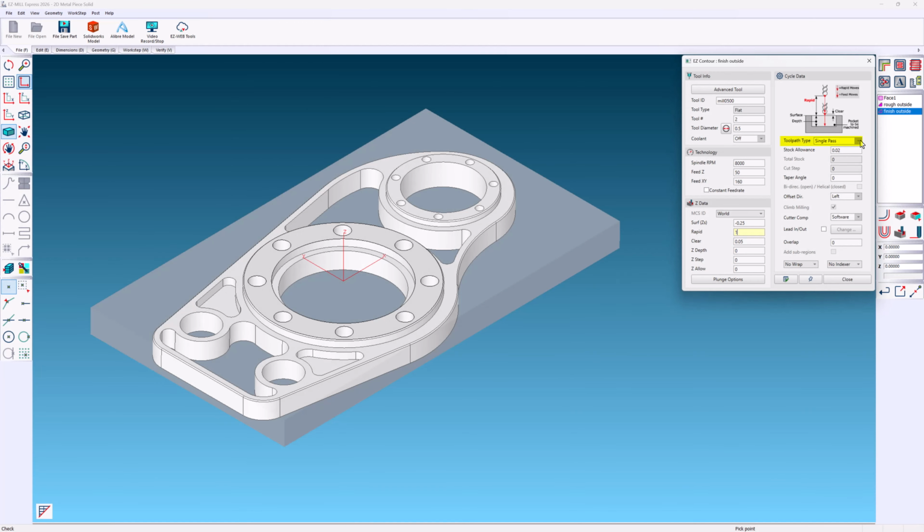Toolpath like single pass is used for those semi-finish or cleanup passes. Multi-pass is one that behaves as a roughing operation with an offset to your profile. You add a total stock for the amount of material you wish to remove and a cut step for the approach. Z-Connect is used for those open profiles. Once you reach one end of the path, CAD-CAM feeds in a Z based on the value in Z step. This action continues until full depth is reached.